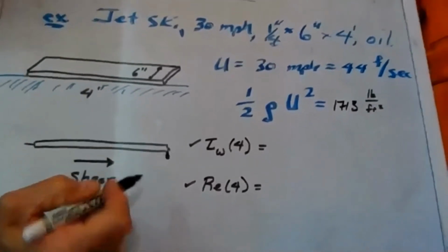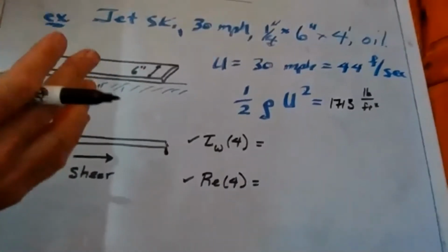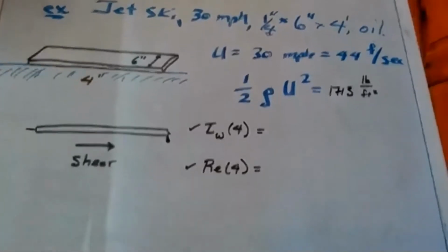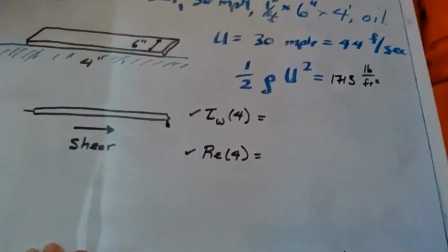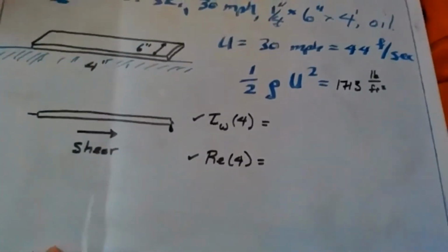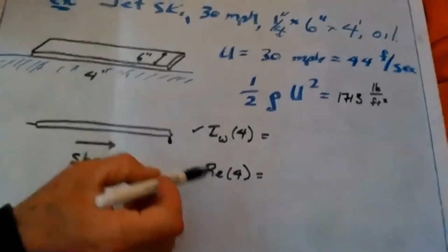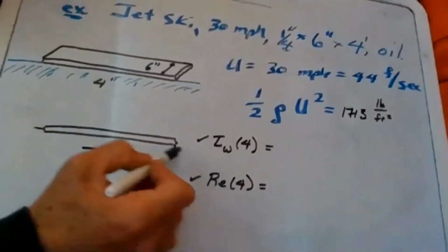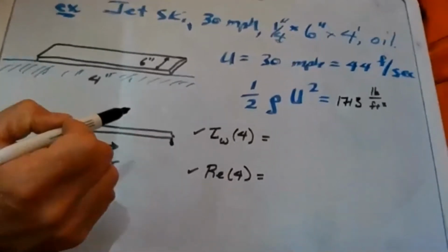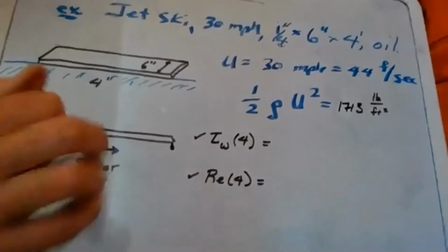Well, as a reminder, we have a formula and it doesn't always apply. It applies when the flow is laminar. So that would be worth doing as a quick exercise reminder. Why don't you go ahead and get the Reynolds number at the end and then see if you can use it to get the wall shear. And I'll get the numbers up there in just a second.